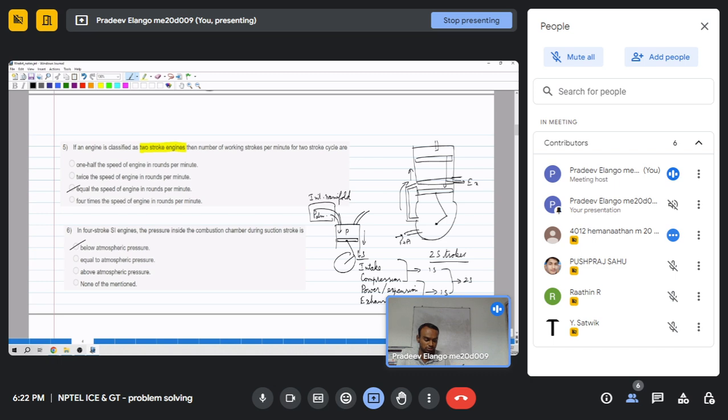And during the exhaust stroke it is the other way. The piston will be moving upward and it will try to compress the exhaust gases, but the port is open, and because of the high pressure of the combustion chamber, the gas flows through the exhaust manifold, which is almost at atmospheric pressure.